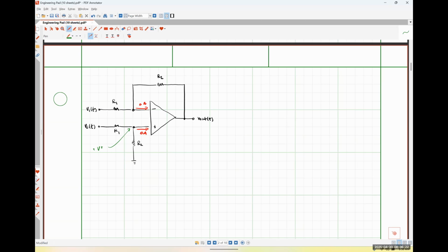Does anybody have any thoughts on how I might find the voltage drop across that resistor R2? So all KCL is going to tell us is that the same current flows left to right through R1 as flows down through R2, which could be valuable because that means essentially that those 2 resistors are behaving as if they are in series.